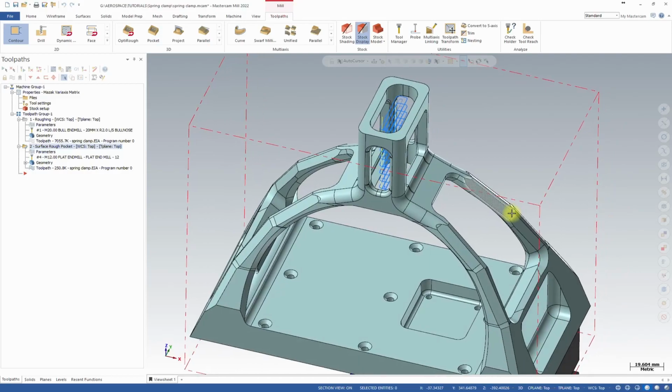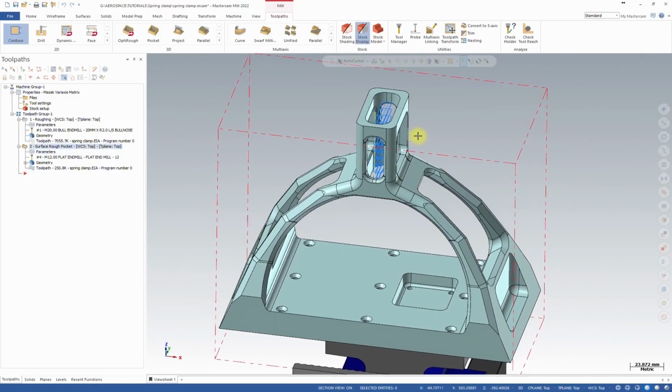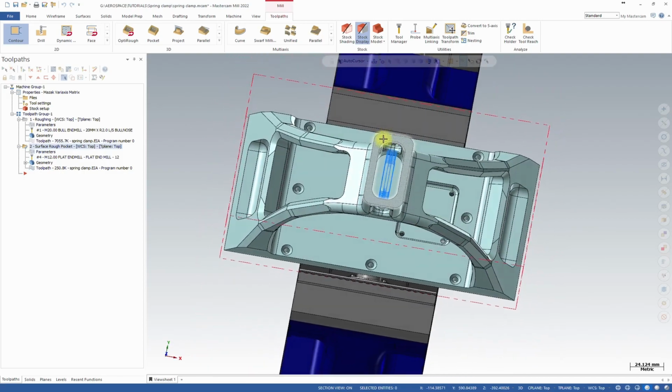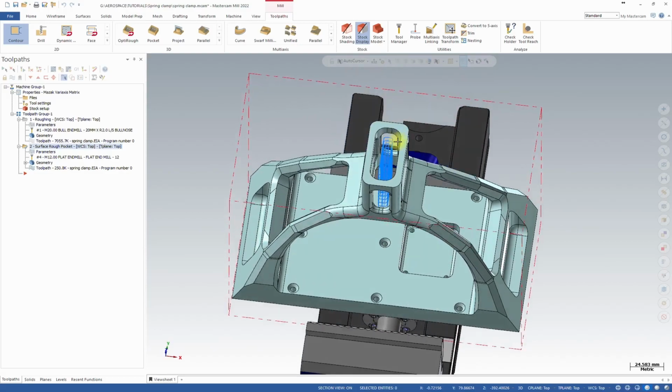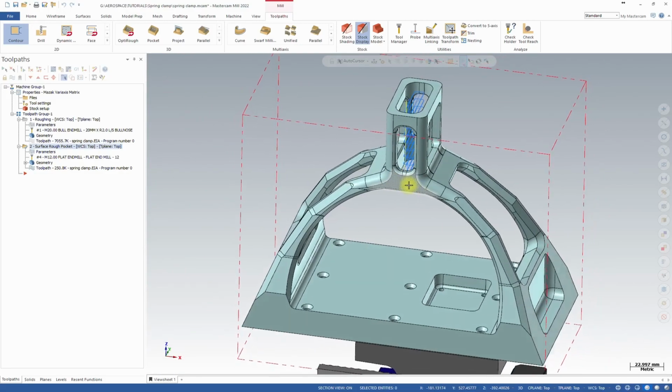Okay, so let's start with this face. If you look at the 3D model, when you use a 2D toolpath or 3D toolpath, you have to tell Mastercam what plane you want to work on, so what side the tool will be approaching the face. So this is my top, and this is my front face. Okay, so this is the front of the 3D model.